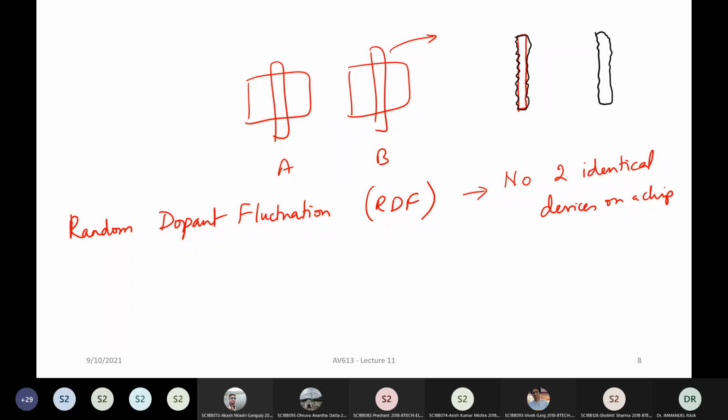So basically you end up with the mean value, which becomes your nominal, and you also end up with a standard deviation. Now the standard deviation is different from process variation. This standard deviation is the variation within the same die for the same process corner. For the same process corner, there is a mismatch between